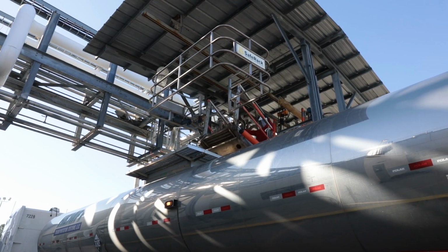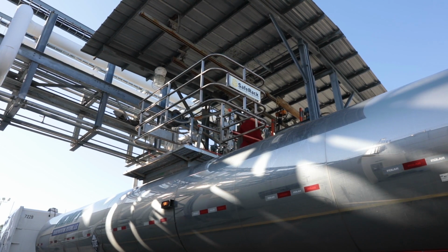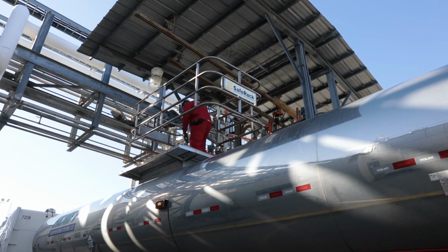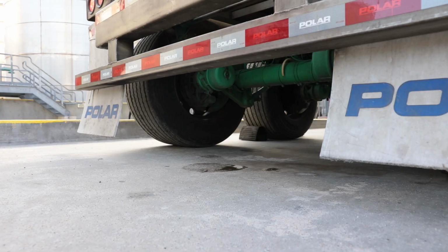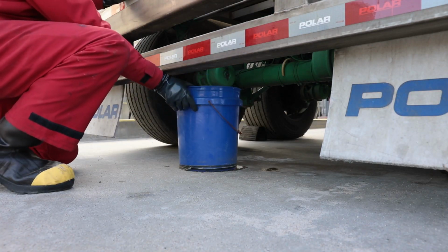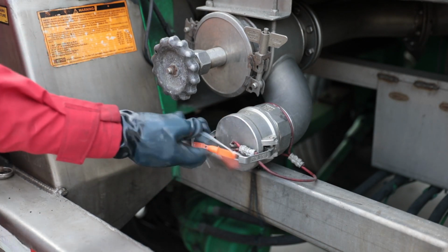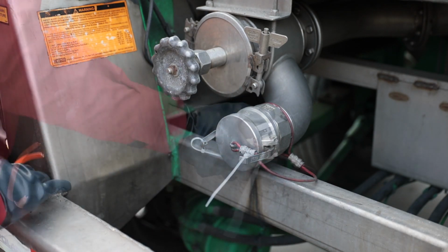For pressurized unloading of a tank truck using pressurized air, obtain a retain sample if needed, then securely close the dome cover. Remove the tamper indicator seals and cap from the bottom unloading valve.